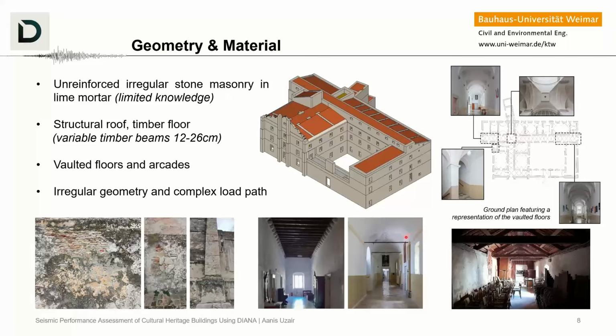Rather, we will assume that we have a good connection, but later on, if this goes into a retrofitting campaign, then we investigate the connections to identify the proper connectivity of different structural components, and then update the model and rerun the analysis for a more detailed seismic assessment.